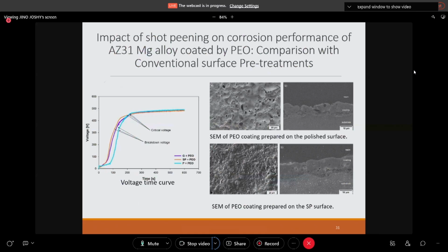Okay, initially it will be in a bright or yellow color, and finally it will be in an orange-red color. Orange-red color means coarse arcing is happening because the layer thickness is very high and we are still passing the current. Okay, and what is the specialty of this coarse arcing? The temperature will be very high, so sometimes a phase transformation is possible. The temperature will exceed a certain limit, so phase transformation can be possible in this coarse arcing region.